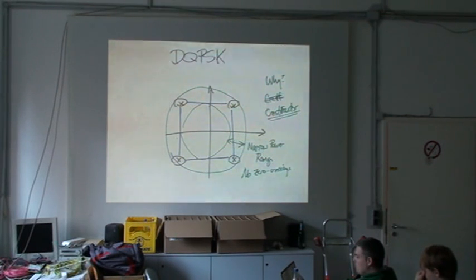Because like I said, that's the best way to think of the amplifier. It's a device that's drawing constant power, converting most of it to heat, and then some of it gets diverted into the antenna. And the more you can control that ratio, the better off you're going to be in terms of power consumption.